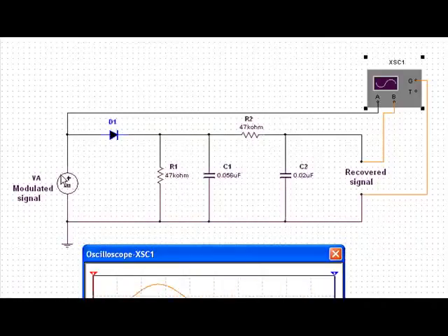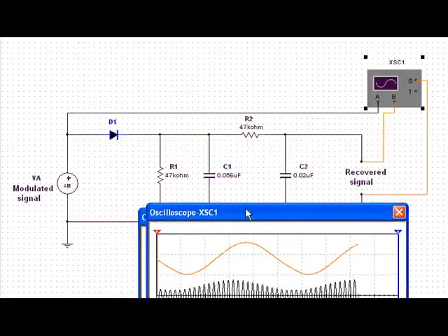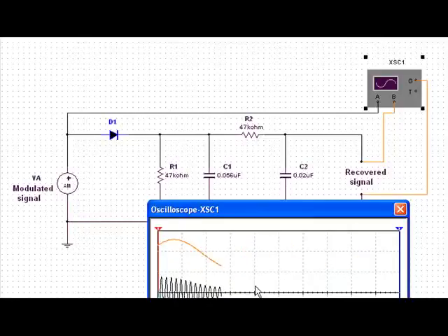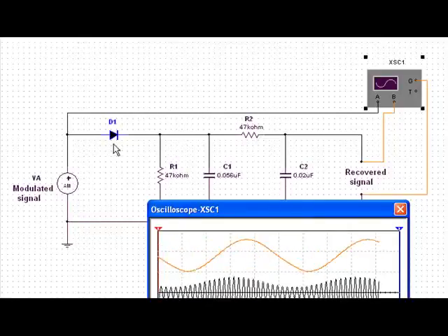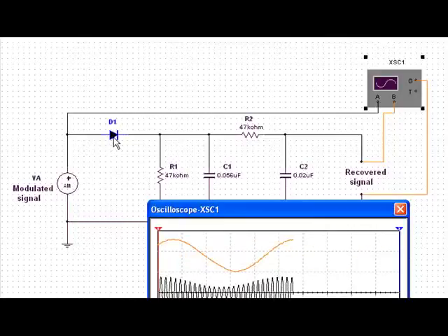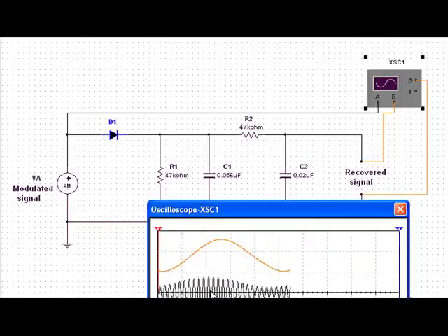First of all, we come in with our AM modulated signal. The first thing that it hits is this diode, and the diode in this case serves as rectification. Since the biasing here would be positive to negative, this would pass the part of this wave shape that's above 0 volts. So we would essentially pass the positive half of this wave envelope.